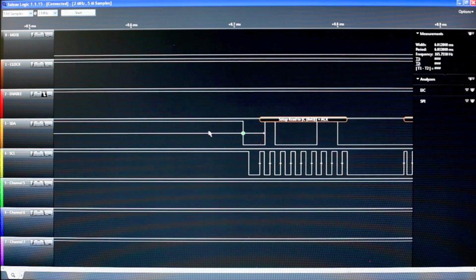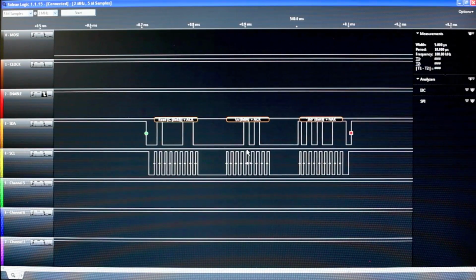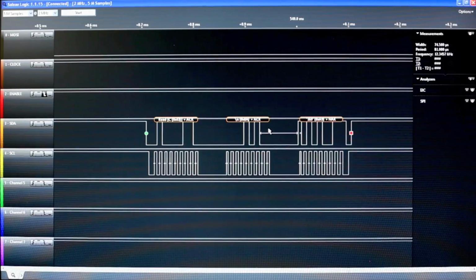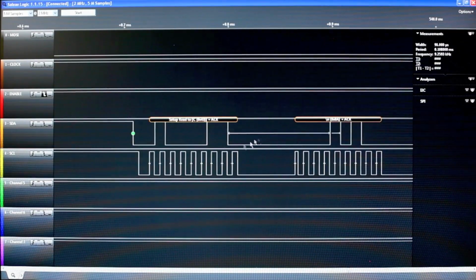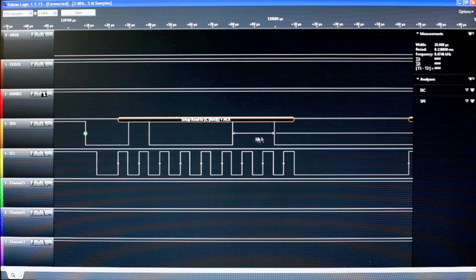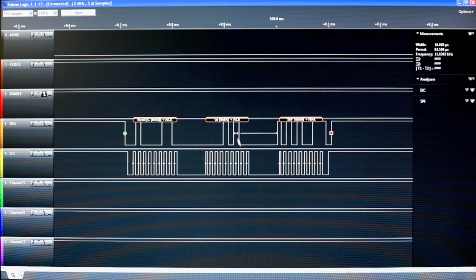Let's zoom in on this. The first 2 bytes are going to be heading information from the HMC6352. Now, this will vary according to which way the wind blows, effectively. The first one is actually the read command. I'm sorry, I was being stupid. So then you set up slave read, and that's what that is. There's our start bit. And the 2 bytes after that are heading data.